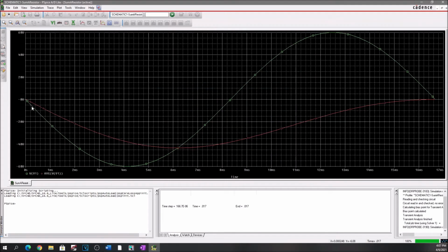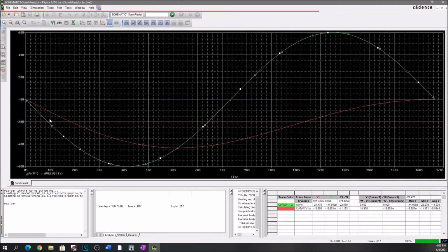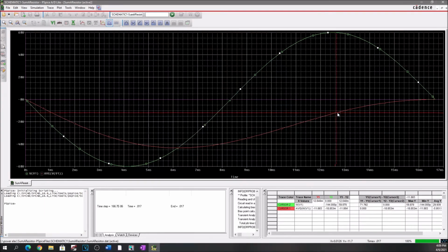Based on the simulation, both power waveforms started in their negative cycle. To measure the instantaneous power, let's go to cursor on, then move it in our waveform to its peak value. From there, for the peak instantaneous power, we recorded the value of 59.990 watts. To measure the average power, let's click here, and we will measure the average power at the stop time, at the end of its waveform. For the average power, we recorded the value of negative 9.3193 milliwatts.